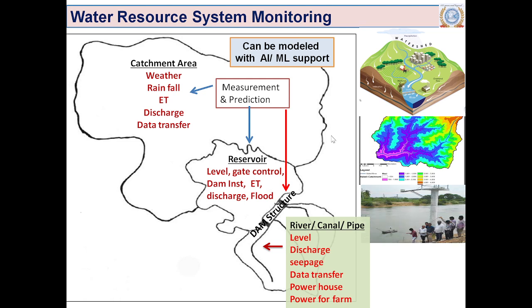Presently engineers are struggling in the real world with this. The latest technology people use today is an acoustic Doppler current profiler to measure the discharge in a flowing stream. You can see how much effort it takes. You have to have a boat tied with a GPS and multi-frequency acoustic signal sensors, and it has to be pulled across the river.